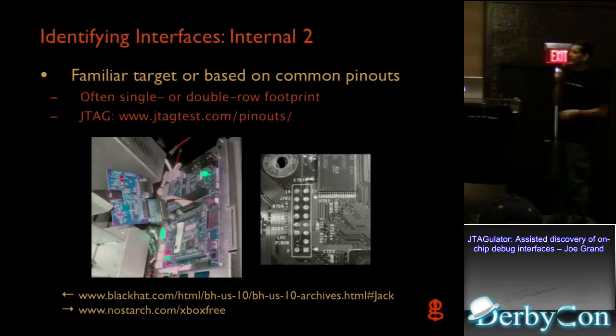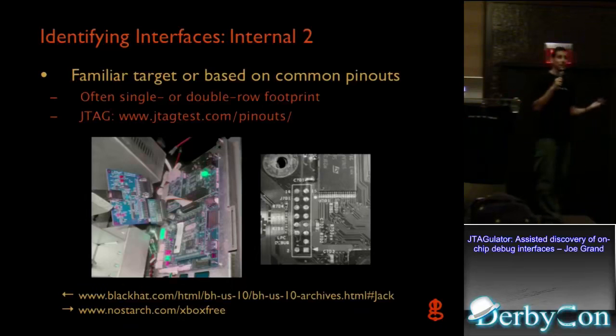The other side is from the Xbox. That's just another example of silkscreen markings that engineers put on boards to make it easier for them, to make it easier for manufacturers, but it's something that we can take advantage of. Anything that's there on the board for an engineer, we can use. In this case, it's a low pin count debug board, and that's a defined pinout as well. So sometimes you get lucky when you open up a board and you know exactly what it's going to be.